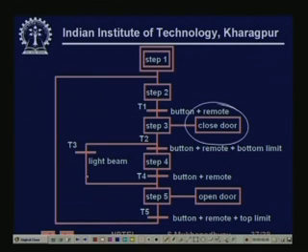Or if the light beam is interrupted, then it will not only stop, it will actually reverse, right. So, immediately it is going to reverse. Here, if you have pressed a button to stop it, and then you press it again, then it will go to reverse. So, you see, we have captured the behavior of the garage door in this form using SFC. You can do a similar thing for the traffic light, let that be an exercise.